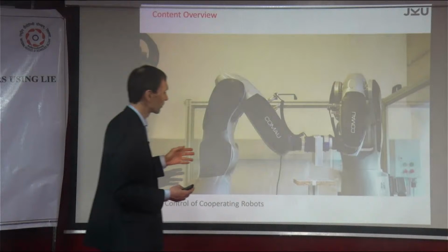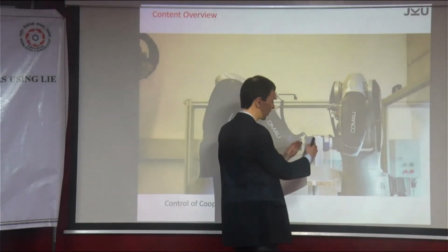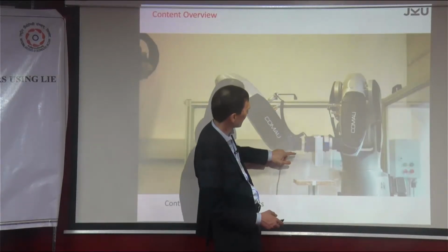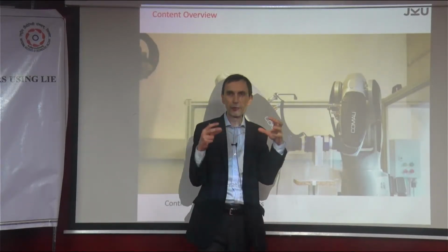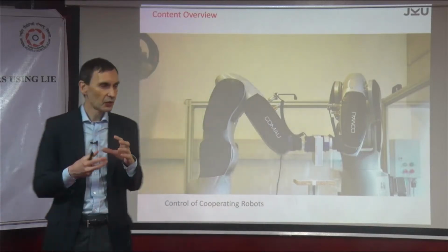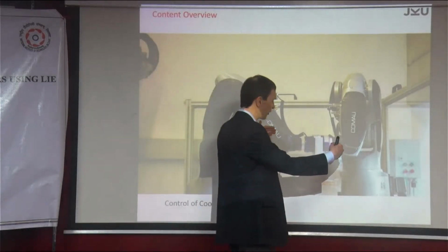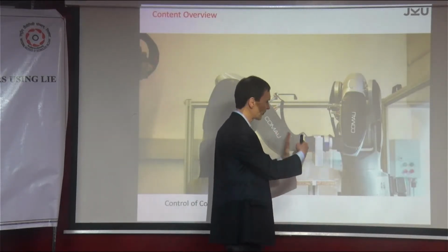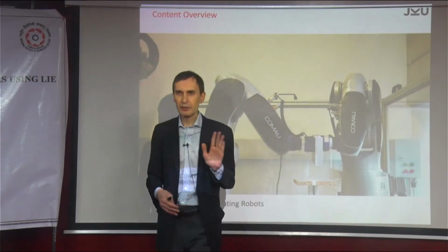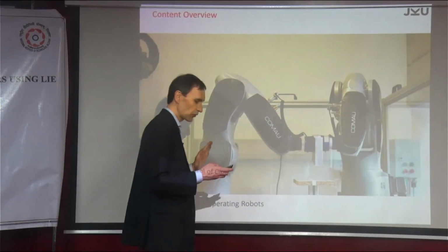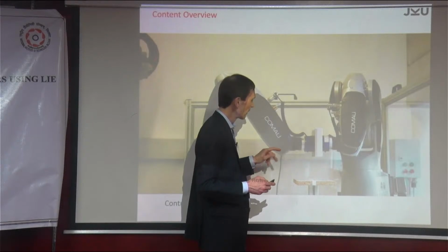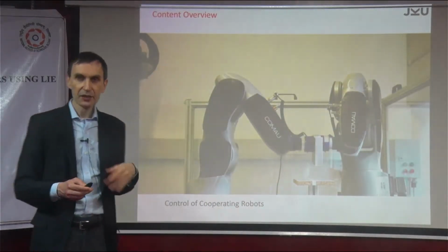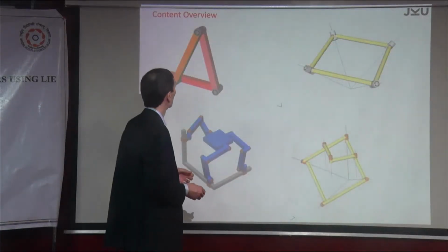And that, of course, is not helping, because if it were a millimeter, plus or minus here and plus or minus there, this would slip. So what you have to do, and this is why you see these blue elements here, these are force-torque measurement devices. What you do here is a kind of real-time admittance control. Essentially, you control a kind of elastic behavior. That is possible, and it's not new per se, but what is new is doing it at this speed, in real time. This is just to motivate you, because without a model, this would not be possible.